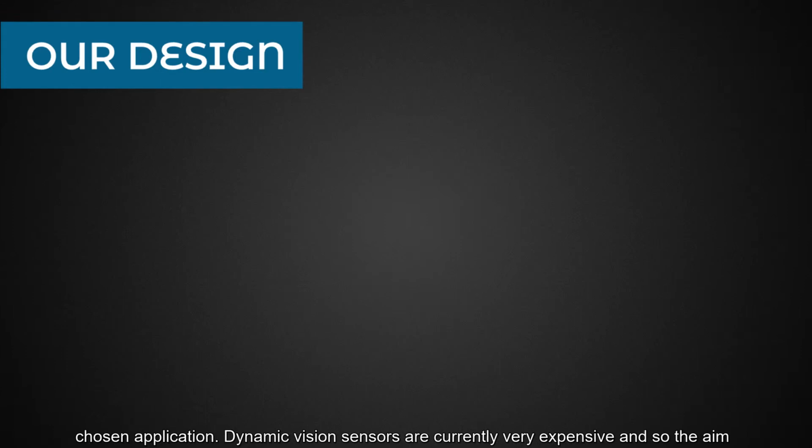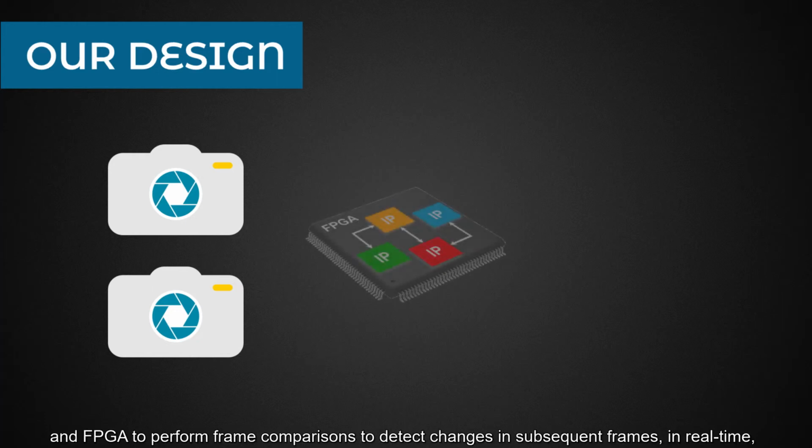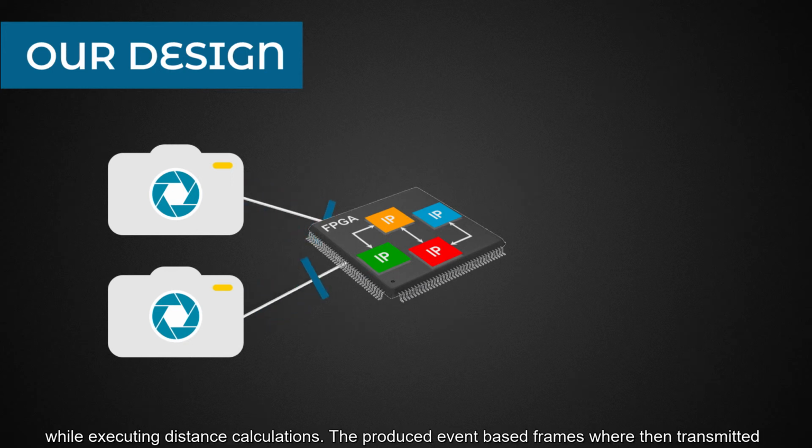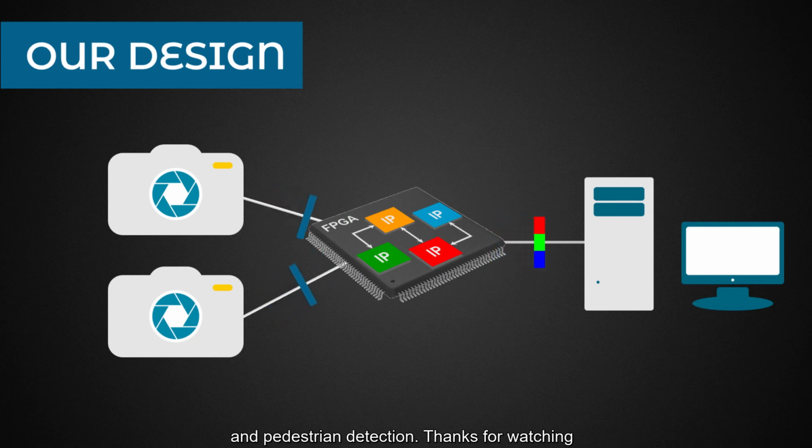Dynamic vision sensors are currently very expensive, and so the aim of our project was to design a low-cost equivalent. Because of our chosen application, we used two cameras for stereo vision in order to incorporate depth information. We utilized an FPGA to perform frame comparisons to detect changes in subsequent frames in real time while executing distance calculations. The produced event-based frames were then transmitted over Ethernet to a high-spec PC that hosted a convolutional neural network for vehicle and pedestrian detection.